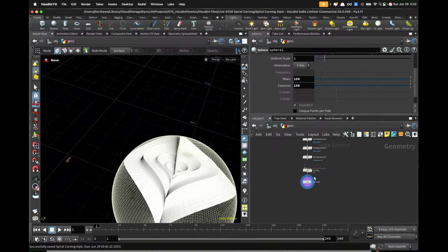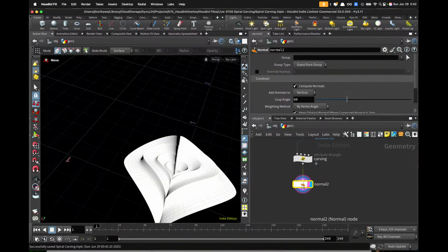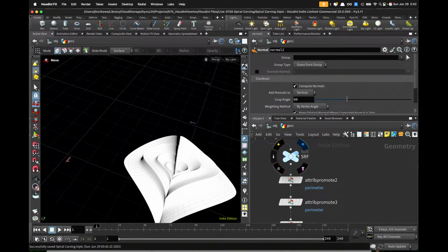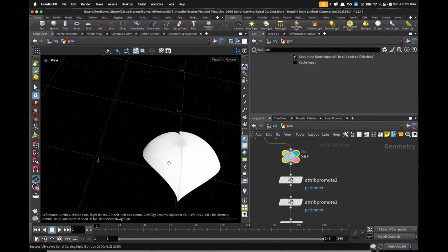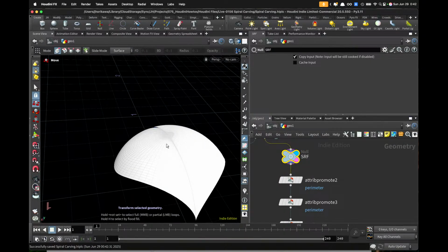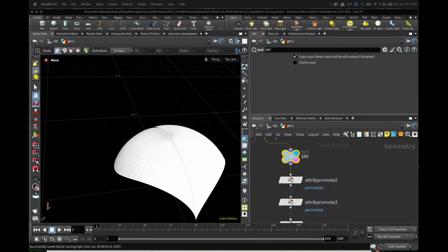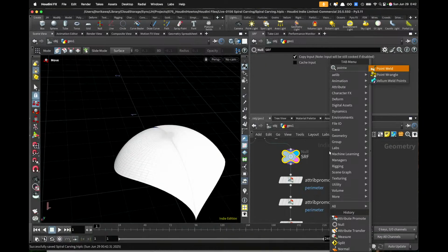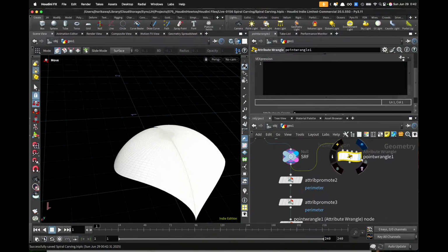So to do that, let's go back to where we have mapped the surface, and I'm going to try to create an extrusion out of the surface and use that to calculate the Boolean between the sphere and the surface. First thing first, I'm going to offset this surface a little bit in the normal direction by some small number like 0.05 or something.